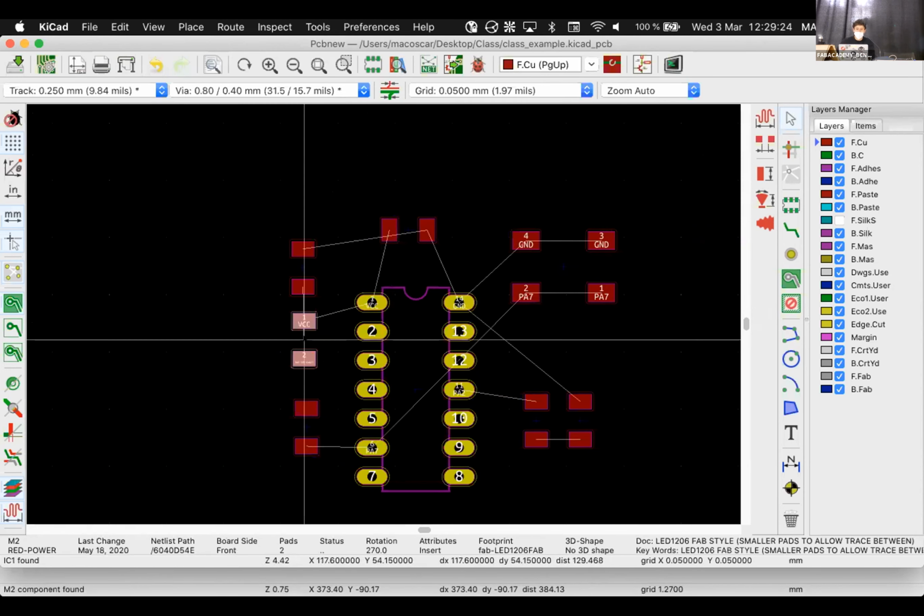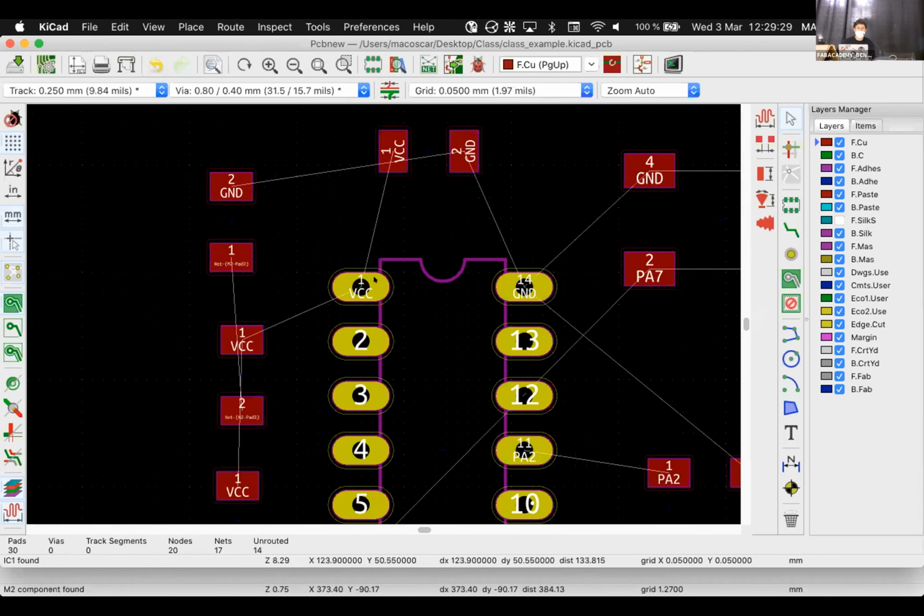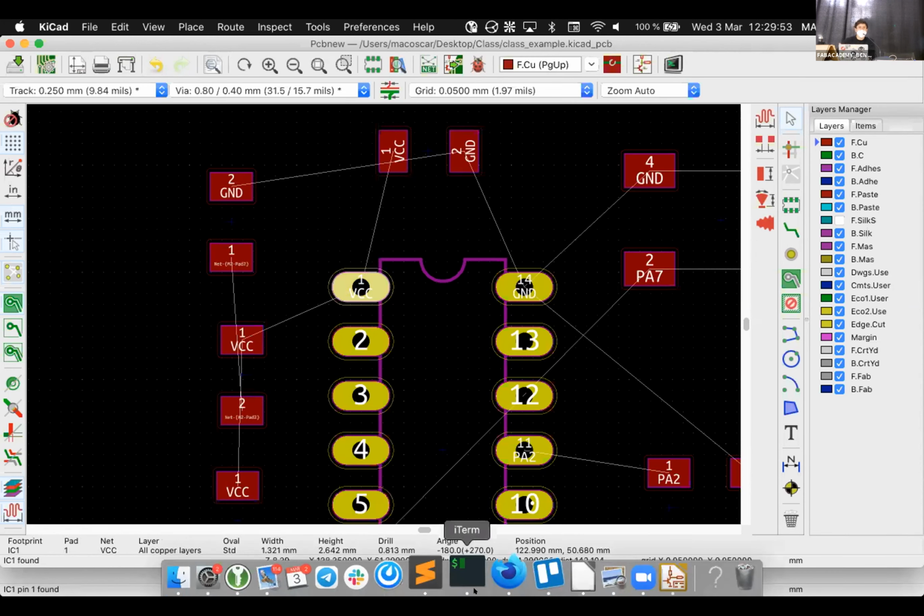Actually, what I just said is not fully accurate, but this means that this yellow pad, we can touch it from the top part of the PCB. This red one is hidden. If we were making a professional PCB, it would be hidden, and we would be able to touch it only for putting the component, but that's it. And this one is intentionally exposed, and it's a little bit more rigid as well, so that you can put things through, like a hole.